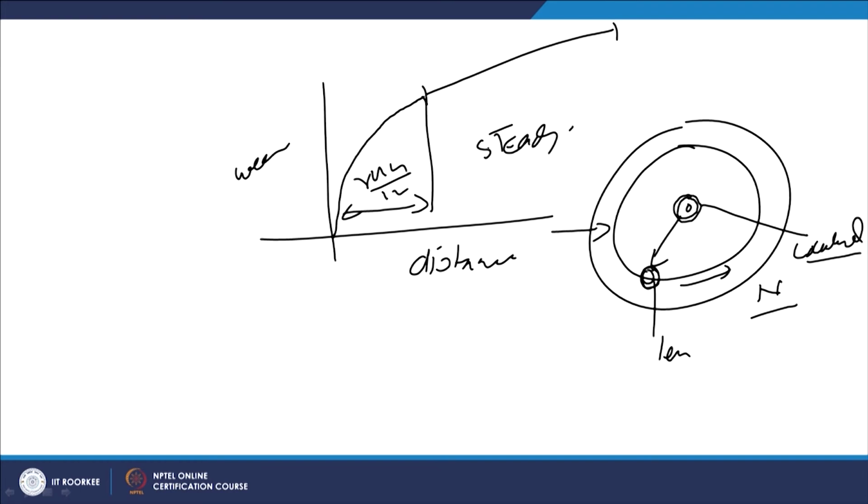For adhesive wear, the test must be conducted for a long enough period so that we achieve the steady state, and this will indicate the kind of material loss per unit sliding distance.